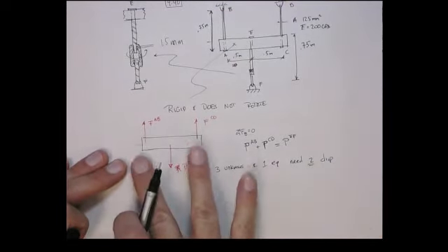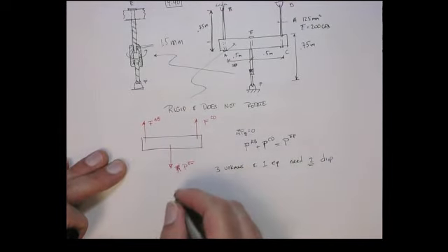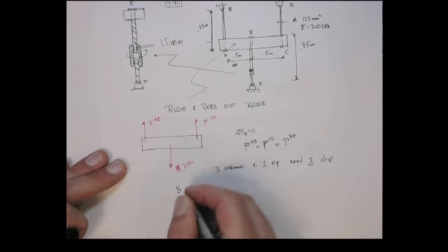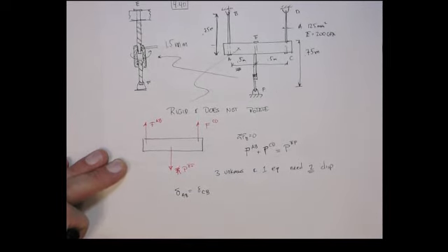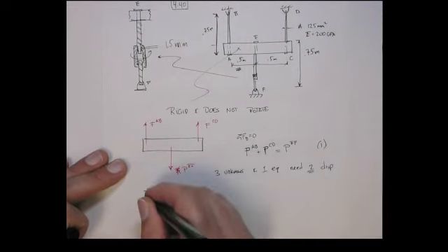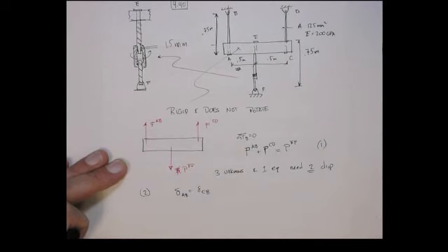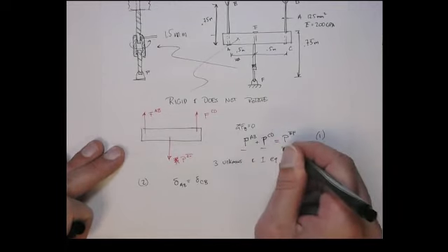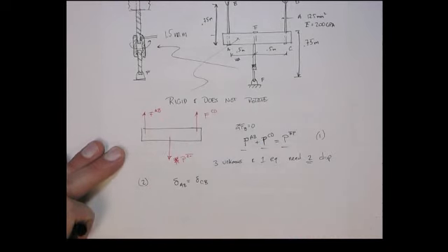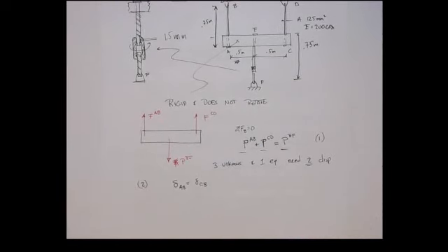You can actually even infer that these guys are the same. So delta AB has to equal delta CD. They have to be equal. All right, that's one. So this is one equation. We can call this equation 2, although I'll probably not use it. You'll see why in a second. And we need a third one, right, to solve for the 1, 2, 3 unknowns. So the third one obviously is going to have something to do with the turnbuckle, okay?